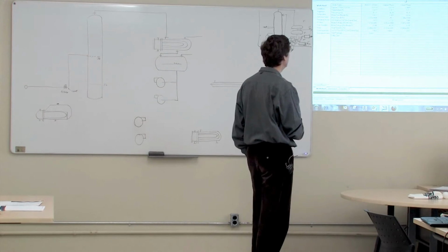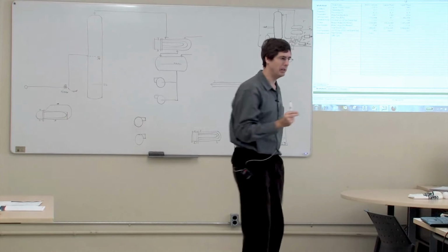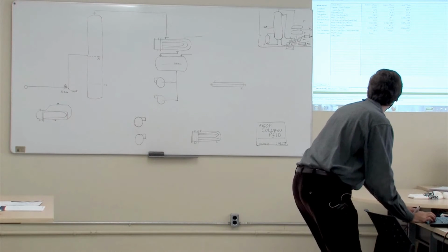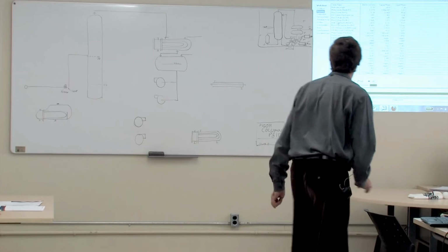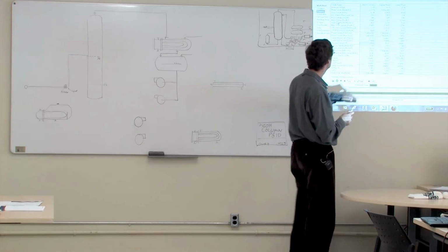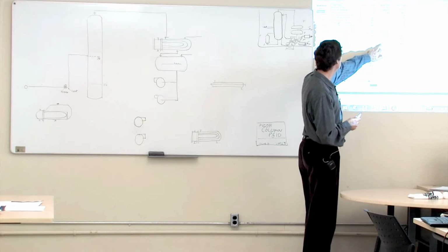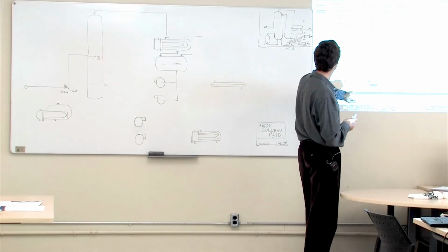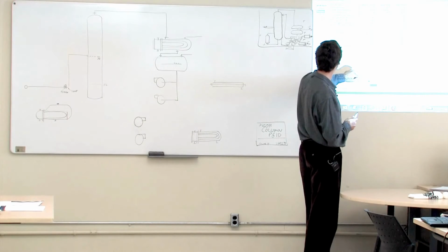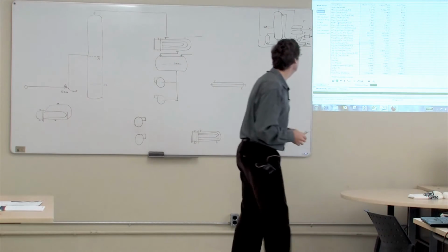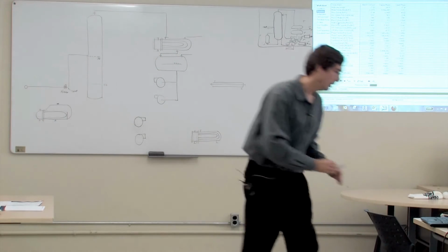So it's a fairly low mass percentage, but in terms of two-phase flow, it's not mass percentage that counts, it's the volumetric percentage. And so what it's really telling me is I've got 29 actual cubic feet per minute, which is a pretty low volume. And the liquid flow rate is not in the same units, so it's 56 gallons per minute.